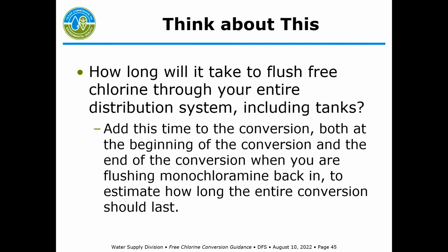All right, another thought question here. How long will it take to flush free chlorine through your entire distribution system, including tanks? Say you figure that out, 5 days or whatever the number is. As I mentioned before, add that time to the conversion, both at the beginning and the end of the conversion, and that gives you an estimate of how long you need the entire conversion to last. So we said you're going to go for 2 weeks everywhere, and it takes 5 days at the front, 5 days at the back. Then you've gotten up to near four weeks or 30 days for the whole conversion.